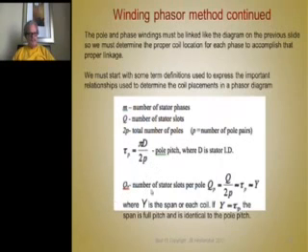So Q sub P is the number of stator slots per pole, which equals the total number of slots, obviously, divided by the number of poles. Where that equals Y, as long as Y is the span of each coil. If Y equals the angle between the stator slots per pole, then the span is full pitch and is identical to the pole pitch.